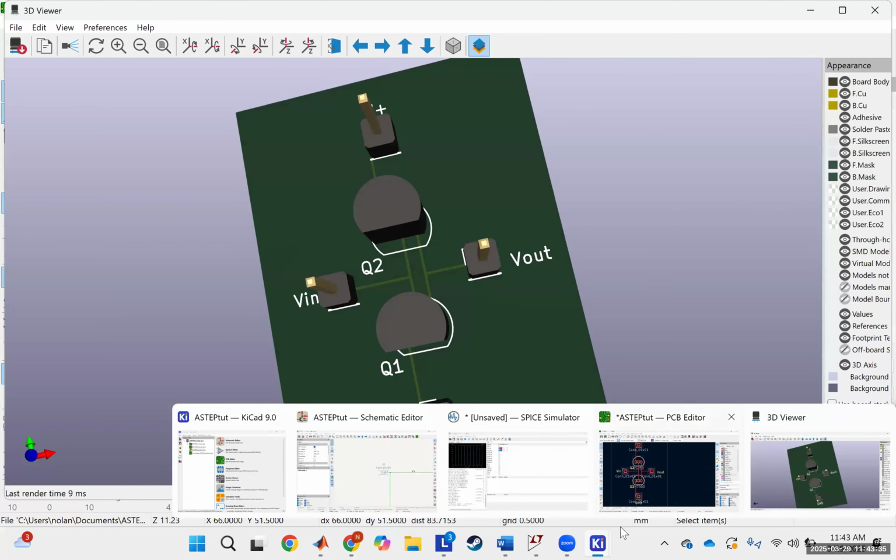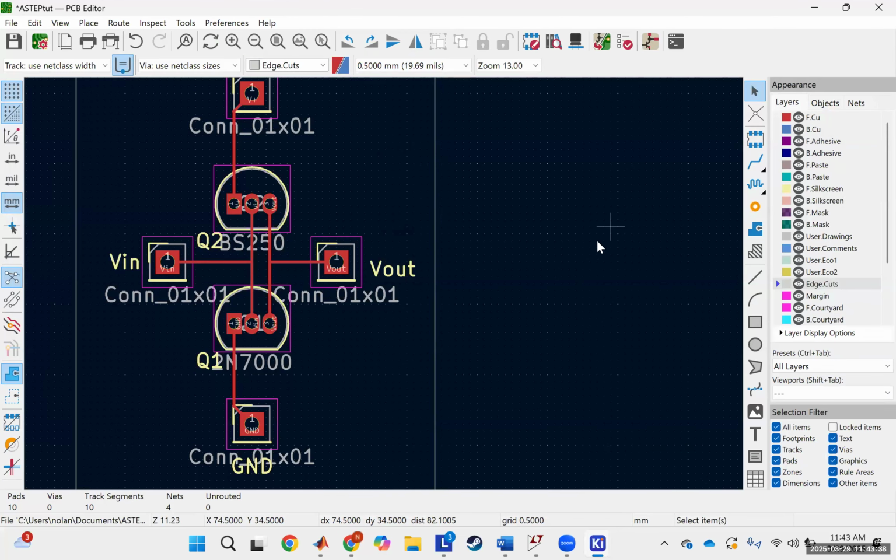One pretty thing to do to make your board a little bit prettier, that I'll usually do at least, is I'll come over here. You'll go to F.Silkscreen, which means your front silkscreen layer. And your silkscreen is kind of like a print layer on top of your solder mask. The solder mask is the green part of the board. It's what makes your board green. And then below that, you have copper, FR4 layers, prepreg, whatever dielectrics that you choose. We'll talk about layer stack ups once I show you my boards at the end. I didn't really want to go over that in the beginning because I thought it might be too overwhelming. And we weren't going to change the layer stack up for this board anyway, so it wasn't really relevant.